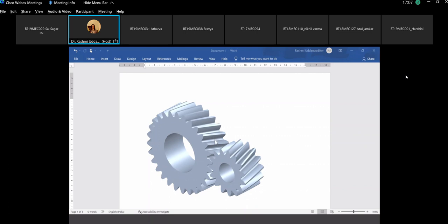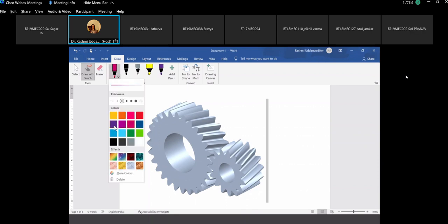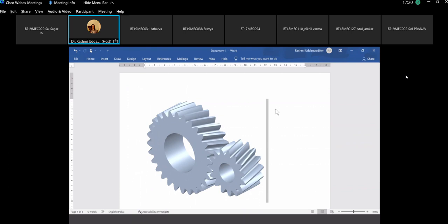And this gave birth to the concept of helical gear. So it's by virtue of its helix angle, or its helical shape, or the orientation of the tooth, that the engagement is quieter as compared to spur gear. It is smoother, it has less jerk, less noise. The first thing that will make you know that this is a smooth vehicle is no noise.